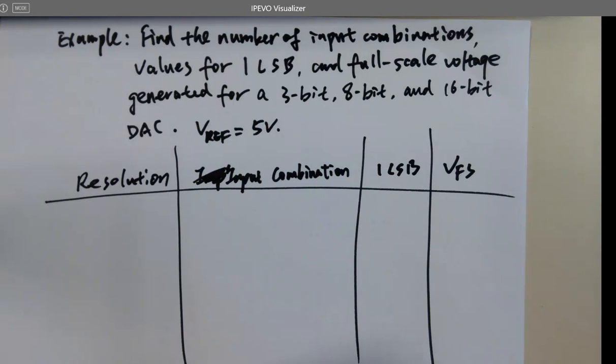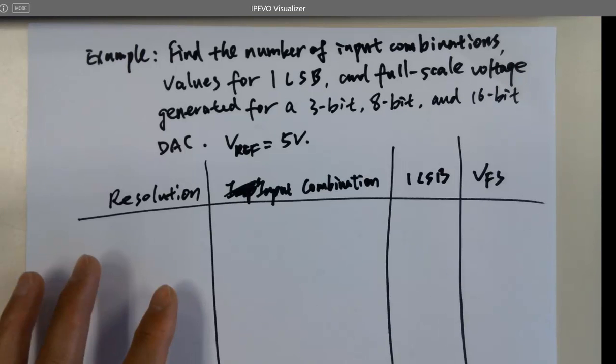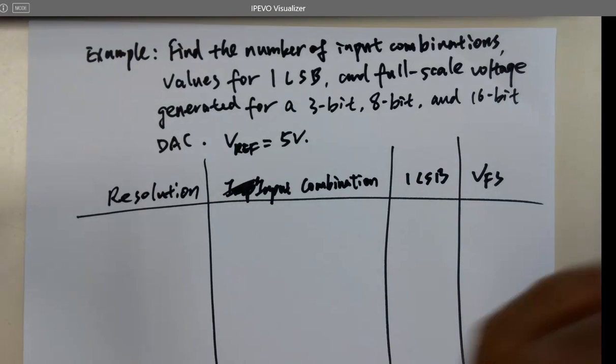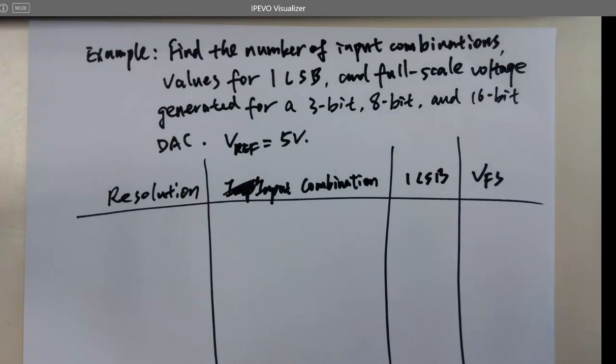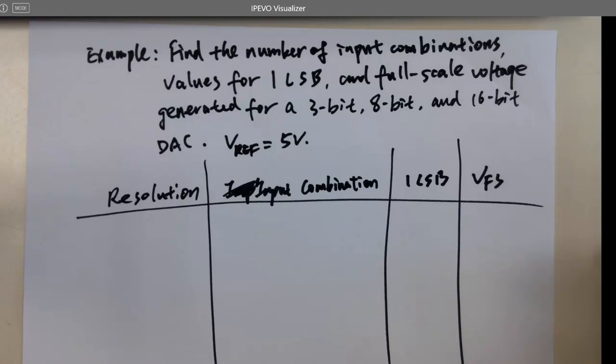If I move a couple of picofarads change, I have to hold. I have to be really careful about that. So any airflow is going to change the capacitance on the board, and the ADC is going to detect it. Super high resolution. Do ADCs work the same way, I assume? Like with resolution, you have 8, 16-bit ADCs?